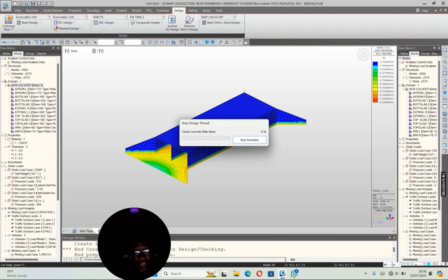Then quality control deliberation on site has its own dilemma. You specify concrete grade, the contractor begins to do design mix. And when they do design mix, you're going to get different quantities based on the specified mix or specified grade of concrete. So you begin fighting, quality becomes a problem, the density control. So many things do happen that need to be done.